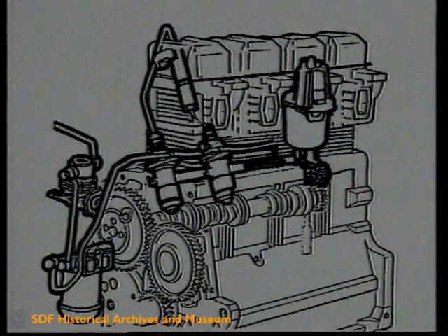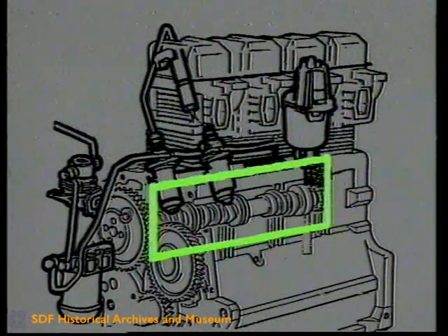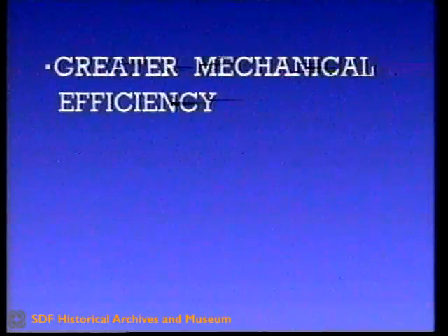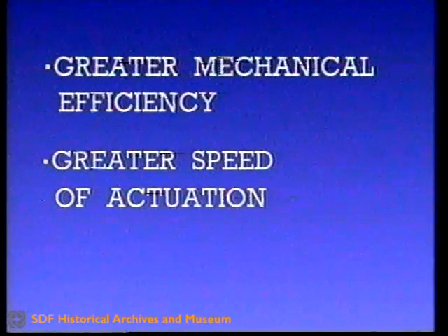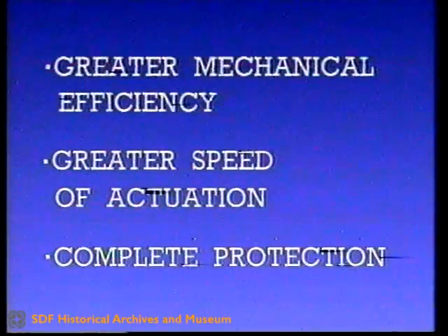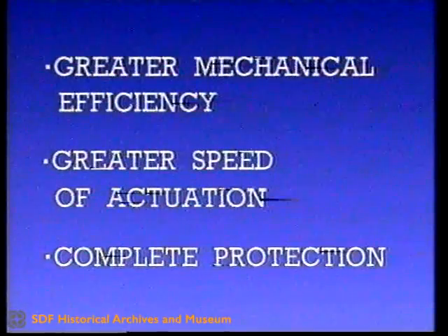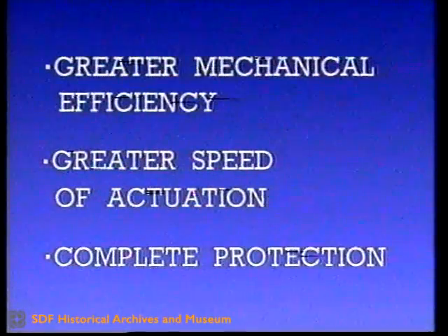Being directly controlled by the camshaft, they do not require a secondary shaft with the relevant gearing to operate them, thus giving greater mechanical efficiency, less friction loss, greater speed of actuation, complete protection against accidental knocks, being immersed in the cylinder block.